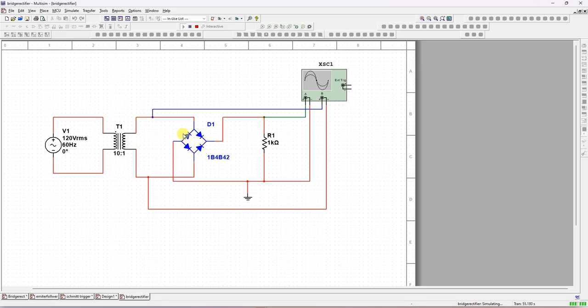These two diodes are reverse biased. Now, in the negative half cycle, this point B is positive, this is negative. So the P side of this diode is connected to this, so this diode is forward biased, and this is forward biased. These two opposite diodes are always the same. These two are forward biased. Now these two are reverse biased. So the current direction is like this. Again in the second half cycle also, current goes down only. So the output is in the same direction only, and it will go like this.